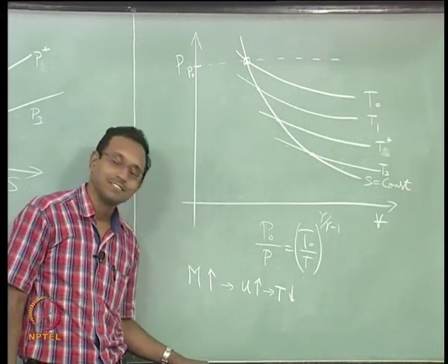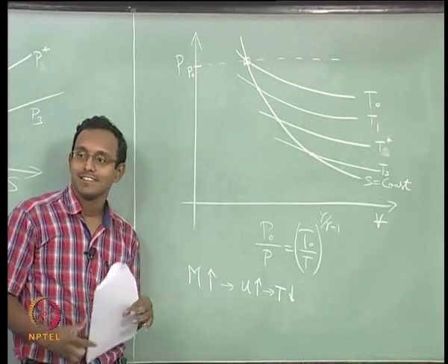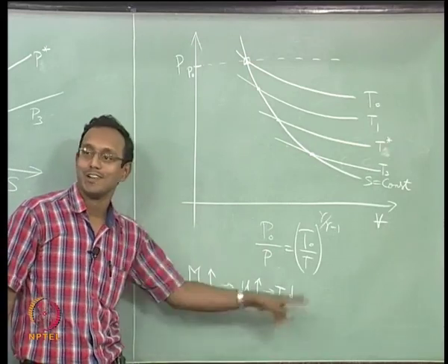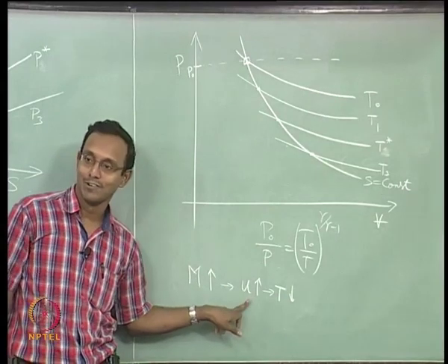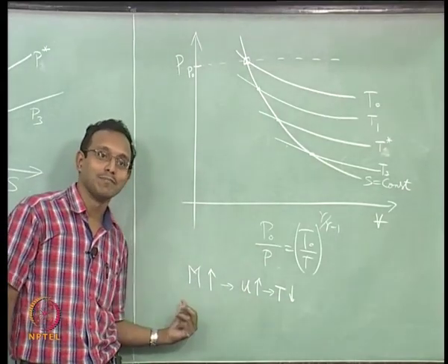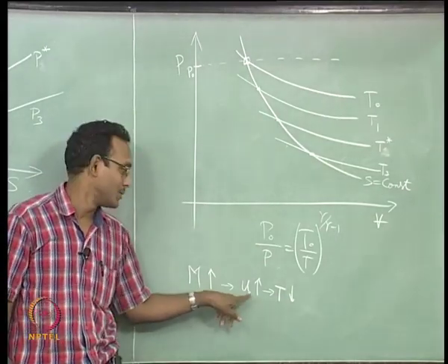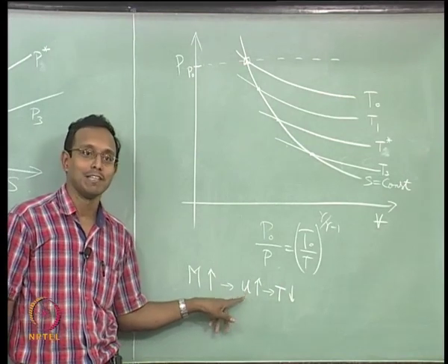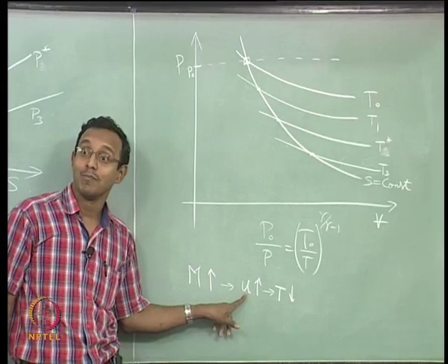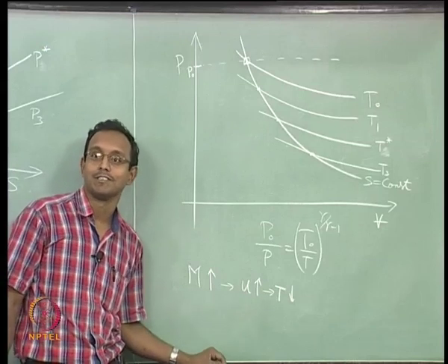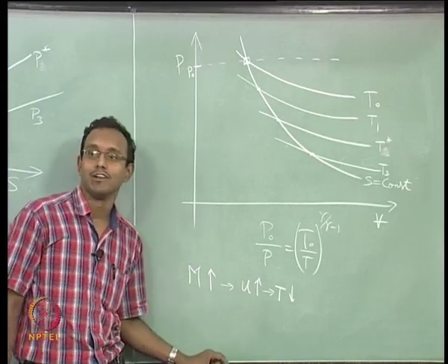It increases. Okay. So, it is like a circular thing. Okay. But actually the way to look at it is, if I accelerate the flow, temperature drops and Mach number increases more than what I do with just velocity. If I double the velocity, it does not mean Mach number doubles. Mach number will go much higher than double if I double the velocity. Okay. That is the way you have to look at it.